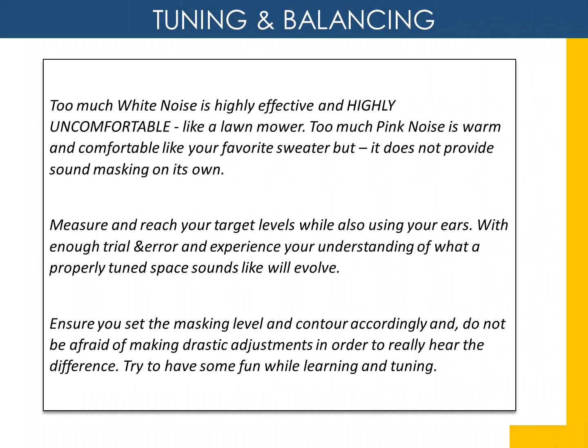Too much white noise is highly effective and highly uncomfortable, like a lawnmower. Too much pink noise is warm and comfortable like your favorite sweater, but it does not provide sound masking on its own. Measure and reach your target levels while also using your ears. With enough trial and error and experience, your understanding of what a properly tuned space sounds like will evolve. Ensure you set the level and contour accordingly and do not be afraid of making drastic adjustments in order to really hear the difference. Try to have some fun while learning and tuning.